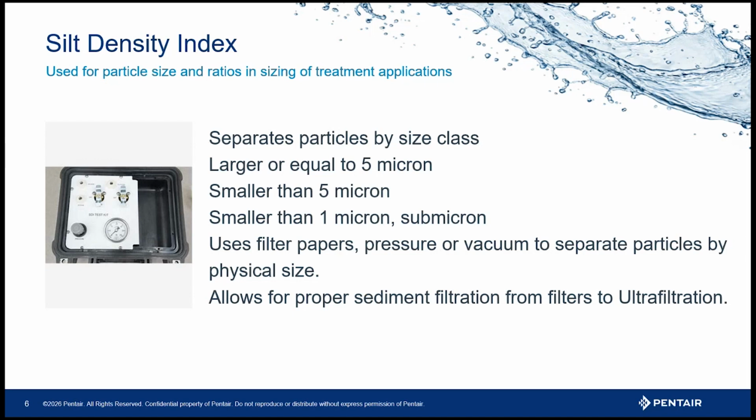So people who have color right after they move into a home, they just bought it, it's been sitting there 6 months, that's a flush-the-plumbing situation rather than treatment. For low pH, pH modification may be the solution for your color. You're going to want to do this as close to the entry of the home as possible in low pH waters to prevent pH damage to plumbing in the house.